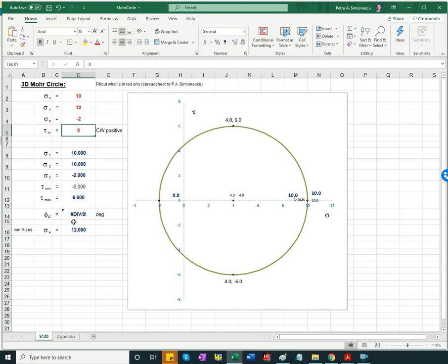Okay. There's ambiguity about the orientation of the principal element, since there's just a point. Actually, the principal element, irrespective of how I rotate it, remains principal element, because tangential stresses in a spherical tank remain the same, irrespective of orientation.